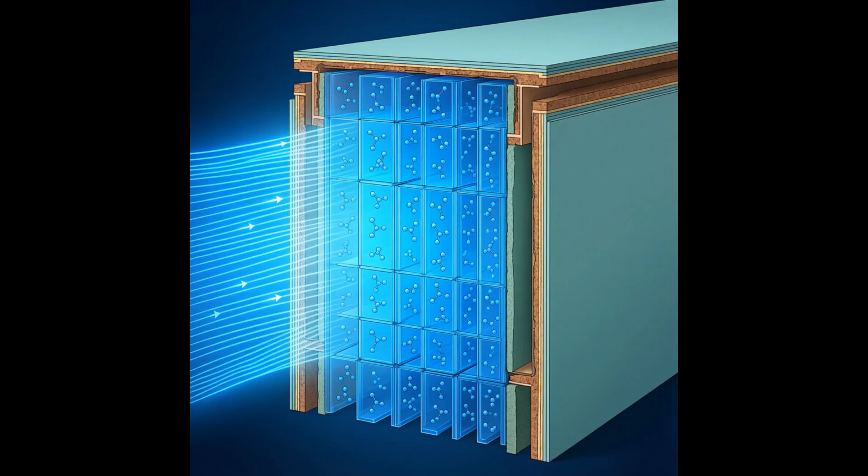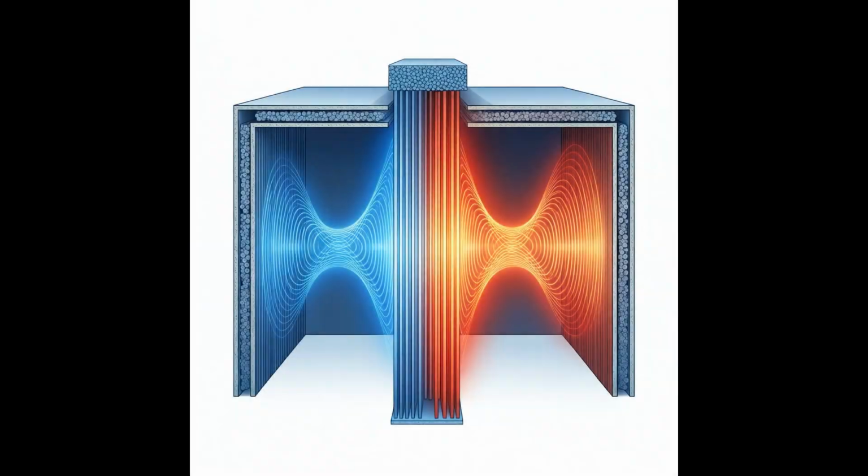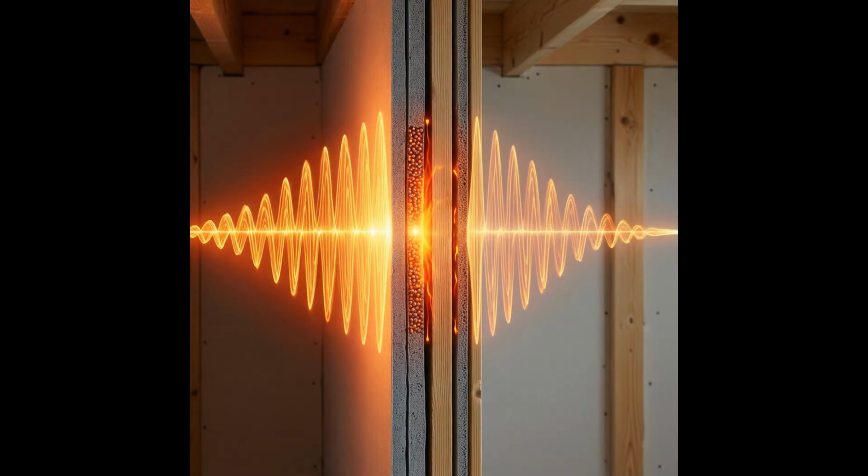The energy does not simply pass through unchanged. Instead, these dielectric substances contain molecular dipoles that attempt to align with the oscillating electric field of the signal. As the wave frequency increases, these molecules rotate back and forth rapidly against their internal frictional resistance. This mechanical motion converts a portion of the electromagnetic energy into thermal kinetic energy, effectively heating the material slightly.